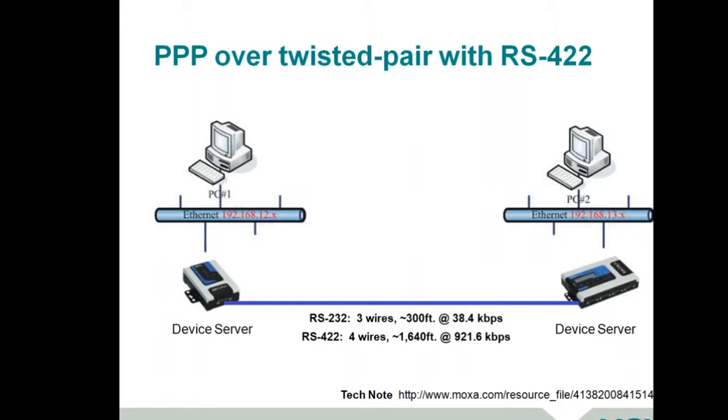You could use RS-485 and run that in half duplex, but you'd only be able to send or receive, not simultaneously. So a little bit about it. This really depends upon the right type of application where you've got a copper cable installed, the speed's not tremendously high, and maybe you've got a real limited budget to utilize a real low-cost solution like this.